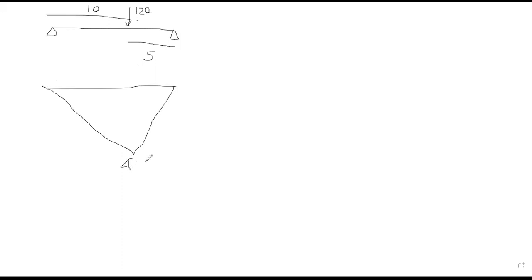So I'll just divide it by the EI, so then I get the M over EI diagram, right? And please consider now the load is not acting at the middle, right? So if you draw the deflected curve, it would look like this, right?